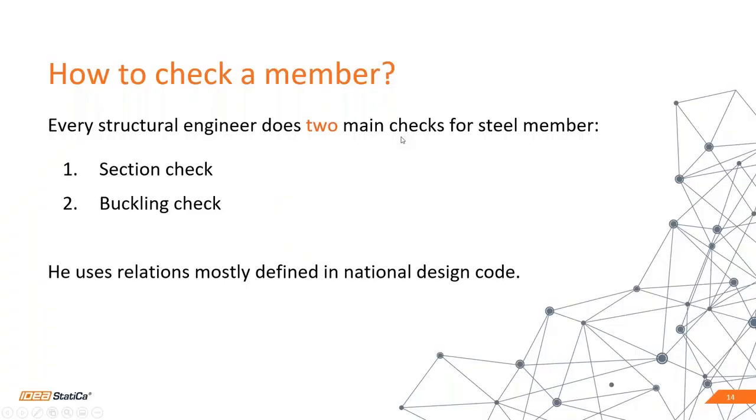During the development process, we tried to investigate the workflow of engineers. How do they check a structural member? Basically, we can separate the check into two stages. In the first stage, the engineer has to check some cross sections, usually the most loaded or the most dangerous ones. And after, they continue to look at the member as a unit, and they have to solve the buckling issues.